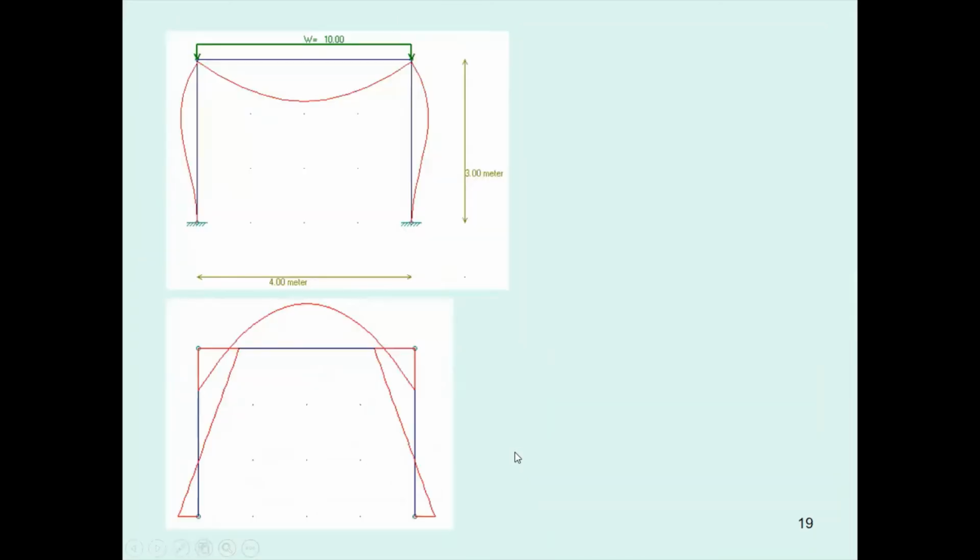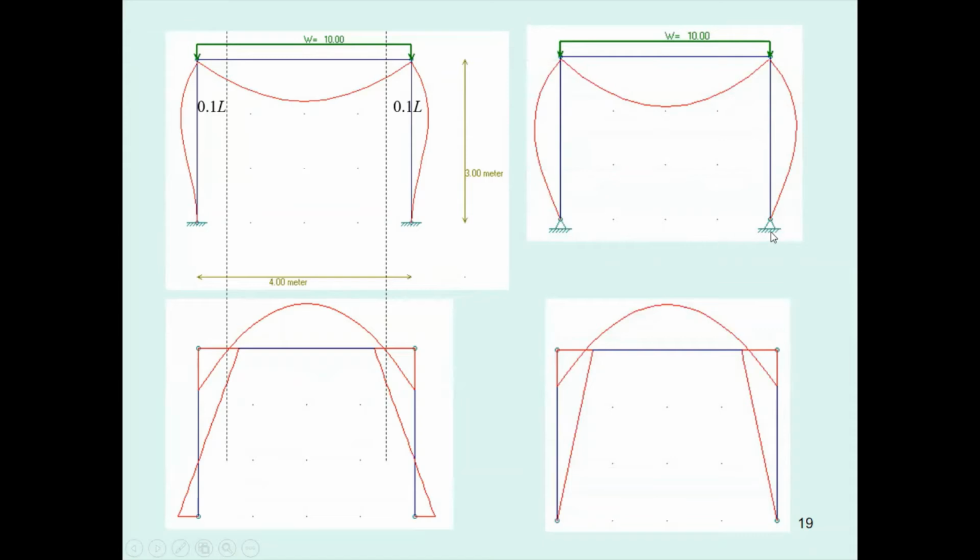By this one you may check, even though the frame has the fix, and the frame has the pin, the point that has zero moment will be very close if your structure is small, especially only one bay like this, or two bay, or just 2-story. This approximate analysis is not for the whole general thing.